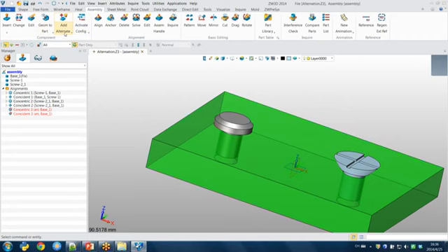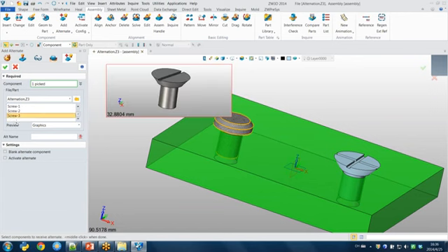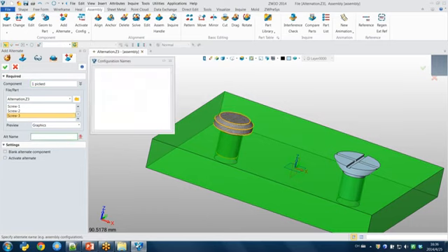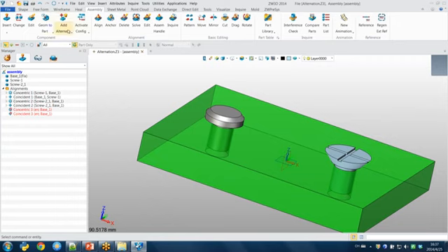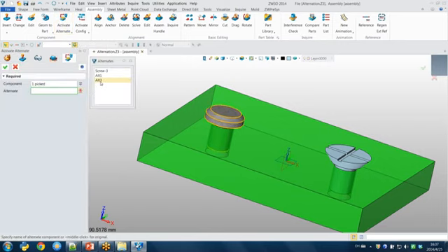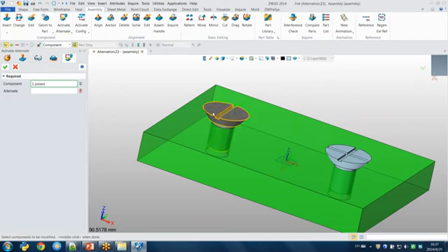So I add an alignment with this one. Select alignment. Sometimes this one is replaced with screw 3, so I give a name, alternate 3. Press OK. After I add the alignment alternate, I can activate this one. Sometimes I want to activate with screw 3, so I can choose screw 3. To change it back, I can also choose the component and alternate 1.